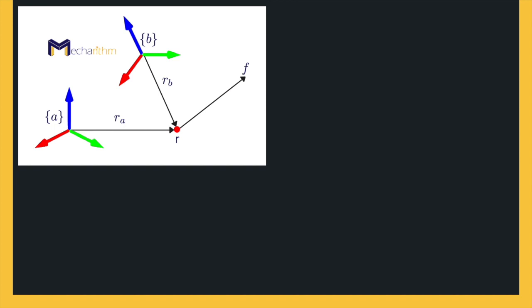Values of the wrench vector depend on the coordinate frame in which the force and the moment are represented. We can represent the wrench in one frame in another frame if the homogeneous transformation matrix is known between the two frames. To learn more about homogeneous transformation matrices and how to calculate them, please refer to the lesson about homogeneous transformation matrices to express configurations in robotics.